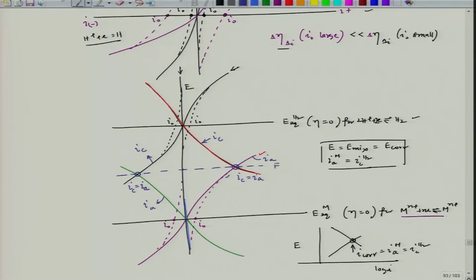So, this potential becomes E corrosion. Now, this is the plot that we get, and if I take a small overflow, that means this will be the steady state potential we will reach, where the rate of cathodic reaction equals the rate of anodic reaction.